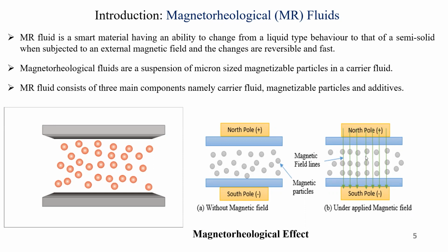In other words, the flow properties of this fluid, which contains a very small amount of iron particles, can be changed by applying an external field. If a magnetic field is applied, it is called a magnetorheological fluid. If an electrical field is applied, it is called an electrorheological fluid. These are the two kinds of rheological fluids that people commonly use. But most of the research is done on the magnetorheological fluid because it is very easy to control and also very easy to manufacture.